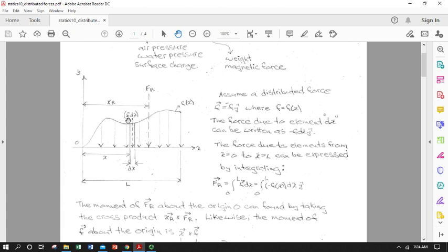Well, just doing a units balance, if f of x, and this is function notation, if our load per unit length is some function of x, so it's up here on the y-axis, and we're looking at an x distance of dx, we know that the actual load, like in newtons, for this little tiny element is the area under this little rectangular slice, right?